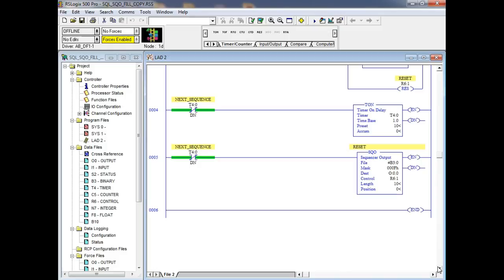Yeah, where you strip off stuff. The OR mask makes sure bits are set in your answer. The AND mask makes sure bits are clear. And of course, what I'm doing is I'm using hexadecimal right here. And I'm only using 4 switches to control the sequence.